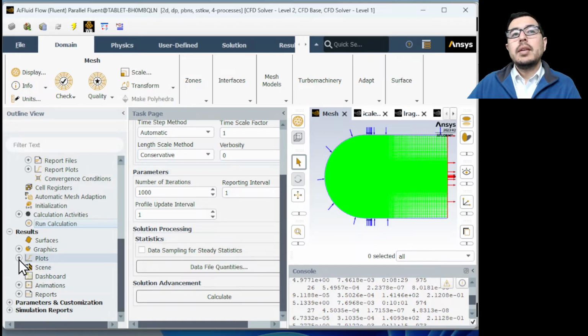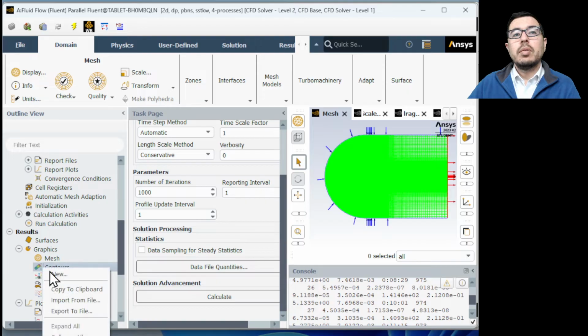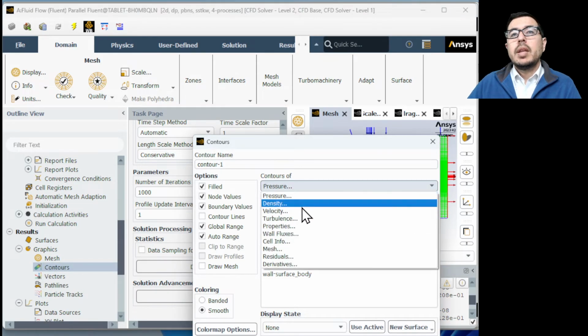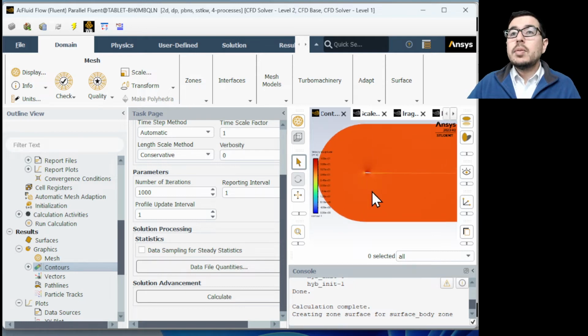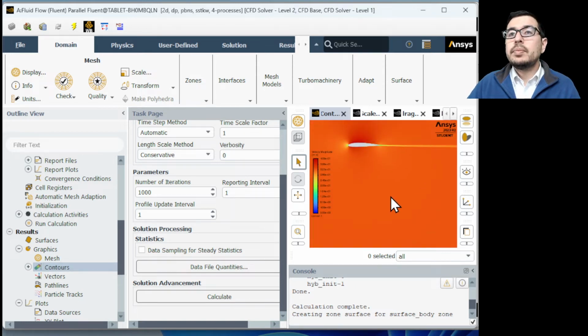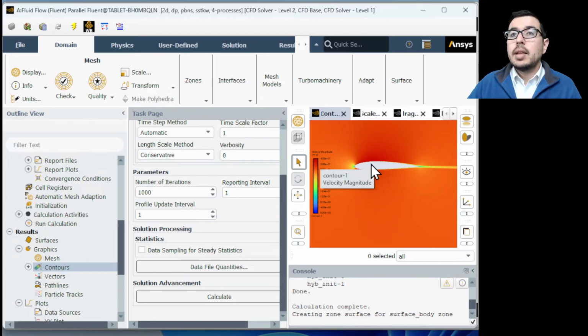We can see, if we go and create a contour plot here, and see if it just does it. Yeah, okay, so we zoom in. You can see this was zero angle of attack, and we have a stagnation point at the leading edge, and then we have essentially a stream coming right off the trailing edge, running parallel to the chord of this airfoil.